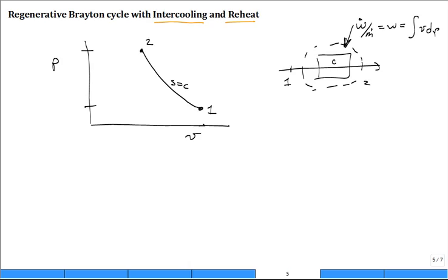It's the magnitude of the integral of v dP. As a review from calculus, when you integrate f as a function of x, you start from x of a, go to x of b, you have some curve like that, and it's the area under the curve. That's the integral of f dx, some value for that integral. Well, here, this always throws students for a loop, because what's on the x-axis? v. What's on the y-axis? P. So what they're doing is integrating v dP.